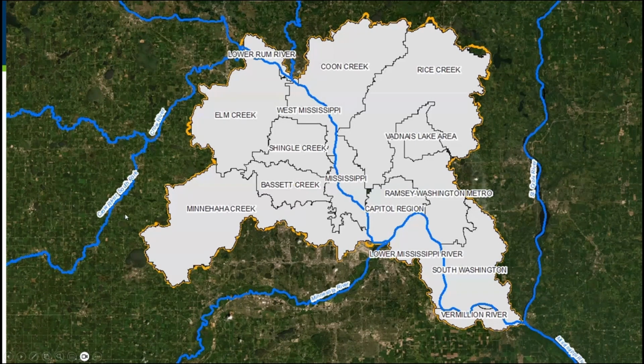If that storm cuts across Minnehaha Creek going straight west-east, going straight down the creek, that's going to have a very different outcome than if the storm goes counter to what it usually does, starting on the downstream end and moving upstream. So when they're doing this future flood risk data modeling, they do Monte Carlo simulations running storm tracks in lots of different ways across the watershed.